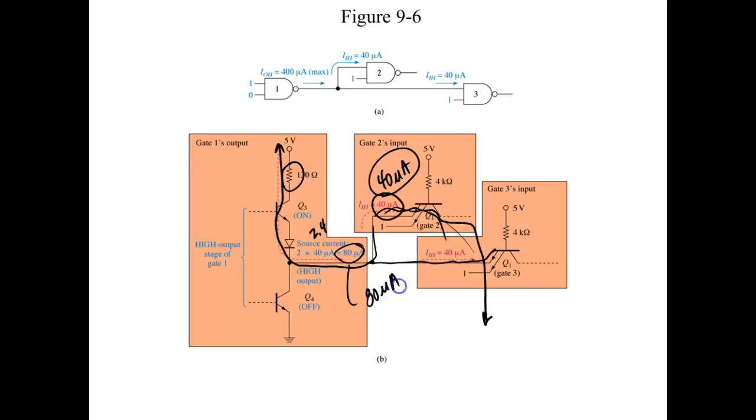80 microamps. So what I need to know is how much current this would be able to source. Here they don't show us that, but we can look at it. This would be I out for a high. Everybody else okay? Now let's say it's 200 microamps. So we could put out an I out low, it could do 16 milliamps, but the I out high is only 200.